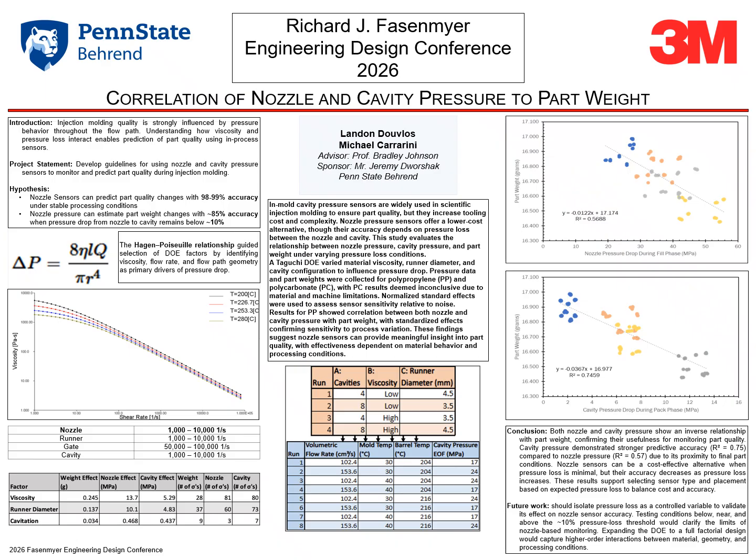and then we applied all those conditions to a Taguchi noise matrix DOE, with our exterior matrix holding hardware changes and our interior matrix holding process changes. That can be observed in the figure in the middle. Quickly taking a look at the results on the right, we have nozzle pressure drop versus part weight and cavity pressure drop versus part weight.